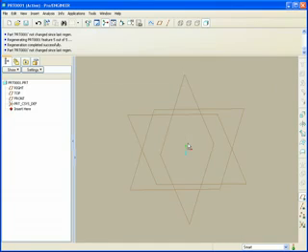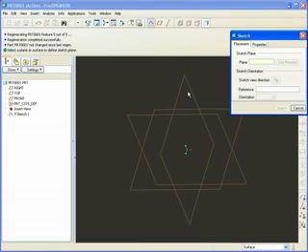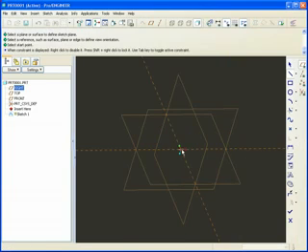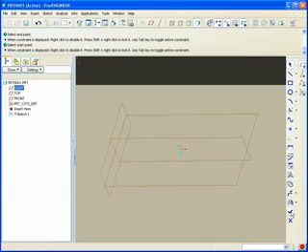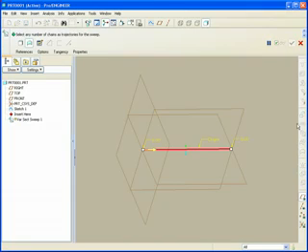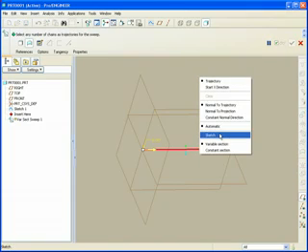We'll start with a regular part and go straight into making a curve. I'll sketch it just on a plane here. Just drop in a line real quick. Give it a length perhaps of 5.5 inches long. Then we'll just jump straight over to the variable section sweep tool, where I right click, go straight to sketch.